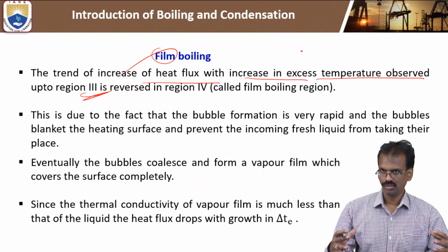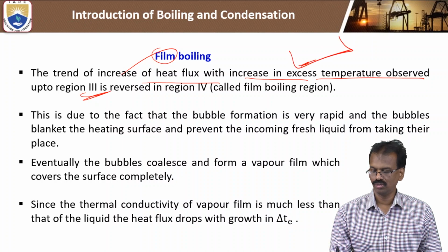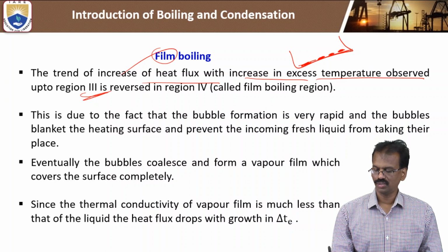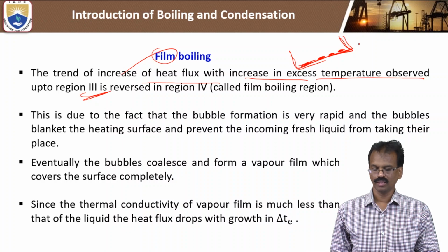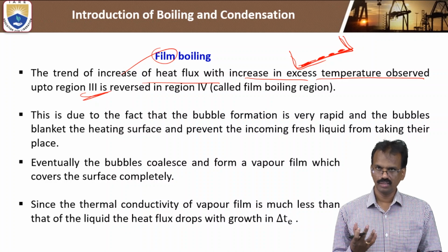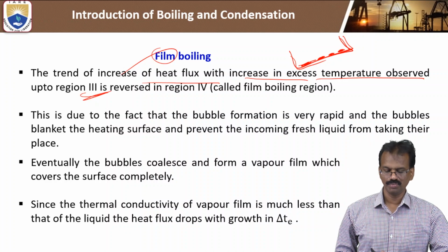Here bubbles are combined with each other and form the vapor layer that is called film on the bottom surface of the surfaces. So these are film pockets. These are unstable pockets of the film formed on the surface of this solid surface. These pockets resist or oppose the heat transfer rate from the solid surface to the liquid. Automatically, the heat transfer rate will decrease.